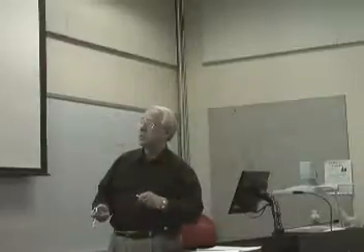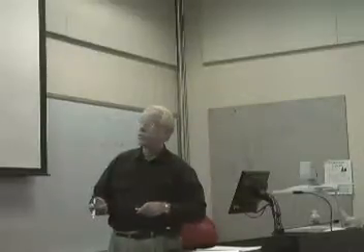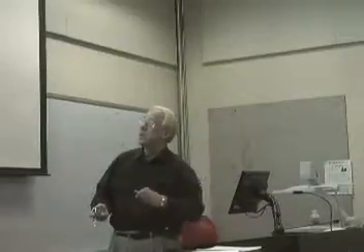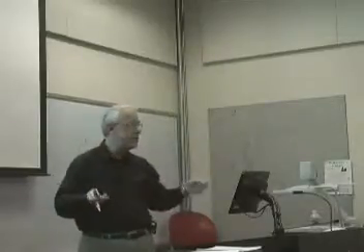So you notice here's the first element, nodes 1 and 2. So that's that little 2 by 2 in the 3 by 3. So if I go to the second element, you see here's the little 2 by 2 setting in the 3 by 3. And then what I want to do is assemble them. So I assemble this into the 3 by 3, the global matrix. So here's my global matrix.